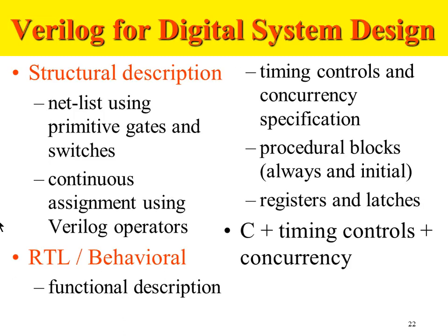Okay. Structural: a Verilog design, or digital design, can be represented in Verilog in two formats, structural and behavioral. What does the structural format consist of? It's a netlist using primitive gates and switches. There are continuous assignments using Verilog operators.